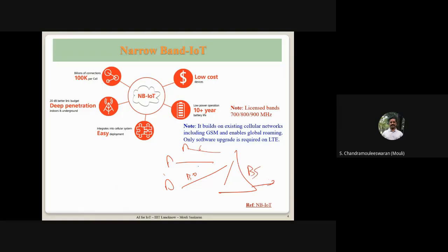If the signal strength is weak, it will sense that the mobile device is not able to send a high-energy signal, or if because of noise less amplitude is received by the base station, then it will bring down the amount of data it can send across. That's why, dynamically, the data rate of your link with the base station comes down based on the situation, the signal strength, and the energy you have on your battery, all those things.